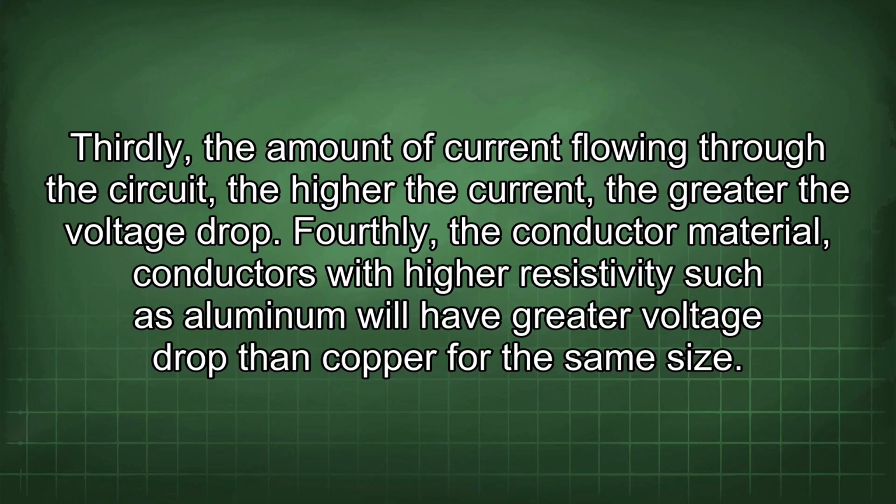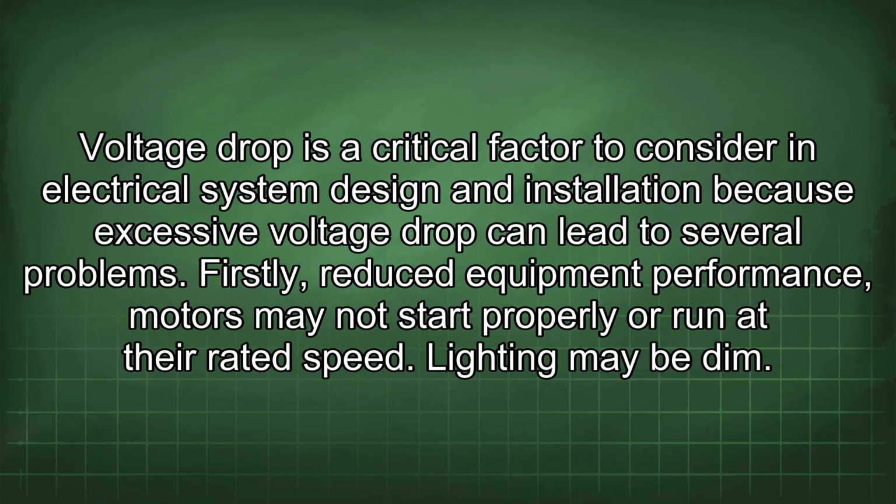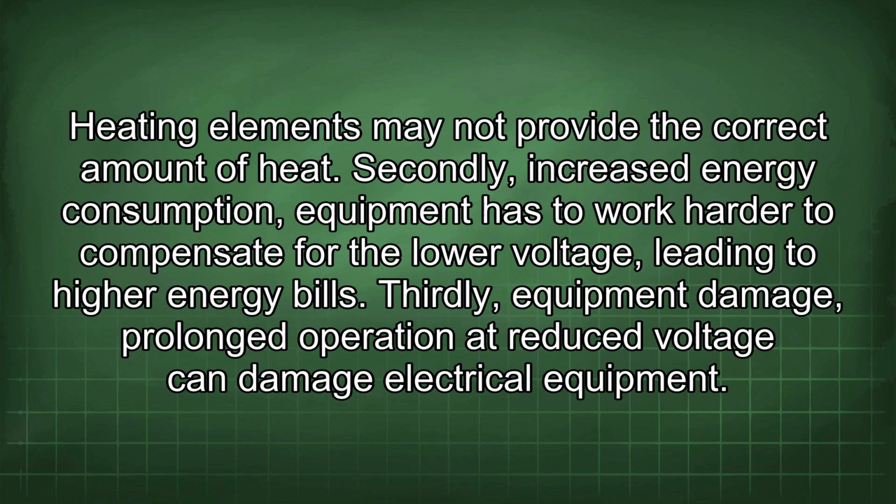Voltage drop is a critical factor to consider in electrical system design and installation because excessive voltage drop can lead to several problems. Firstly, reduced equipment performance. Motors may not start properly or run at their rated speed. Lighting may be dim. Heating elements may not provide the correct amount of heat.